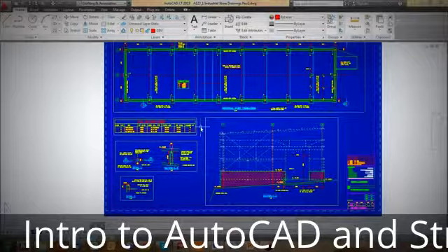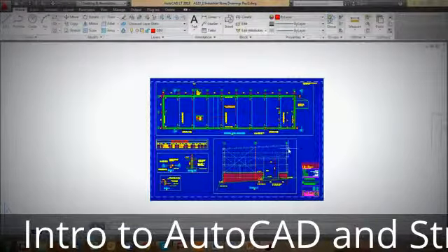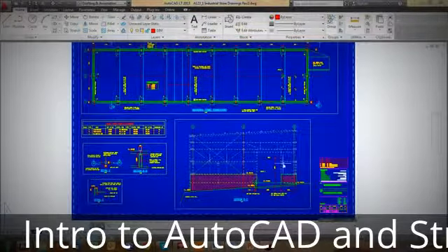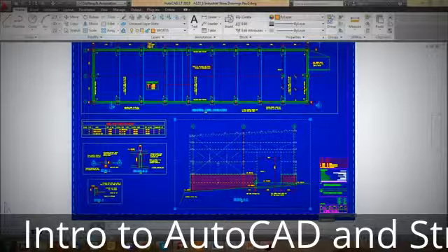You don't have numbers all over the show, and it also means you don't have to change things each time, because when you create it, it's so small or so big you can't read it. If we want to now go into a viewport, I'll click on it. It is now inactive until it has a thick line around the side. It is locked. If you look in the bottom right corner, it says lock, unlock viewport.